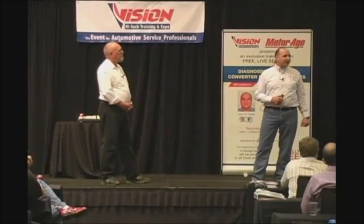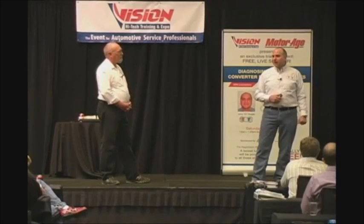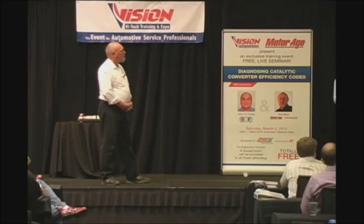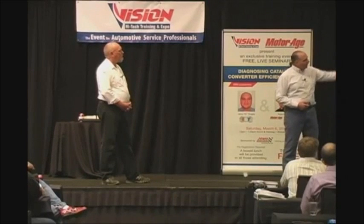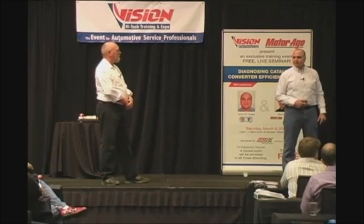Honda also has a gig like this. Not on all their cars, but on a car line. Okay? So you need to look at stuff carefully. Information is king. That's the name of the game. So, new CAT. Another one, a 420 here. This one, 420, 50% load, 186 degrees, fuel trim, not that crazy. 72 miles an hour is when this set it.